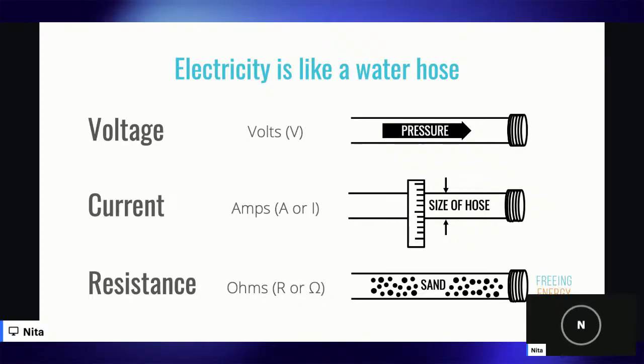That's why it is important to have the proper voltage rating, which is something that we'll be looking out for in our inspection. Your outlets, your TVs, small appliances, all of that kind of stuff is typically going to require 120 volts. Your larger appliances, your dryers, your ovens, your AC condenser, those typically require 240 volts.